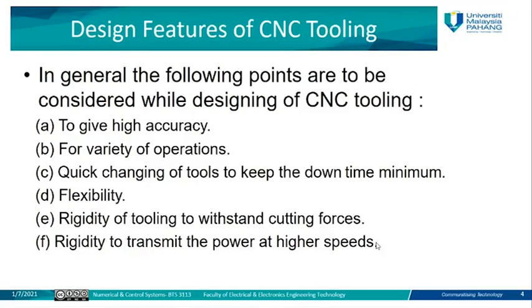Quick changing of tools. If you are going to perform multiple operations on the same workpiece using different types of tools, you need to consider the time taken to change from tool 1 to tool 2 or from tool 2 to tool 3. This time is important when you produce, for example, hundreds or thousands of parts. The smaller the changing time, the better it is to use such a tool.